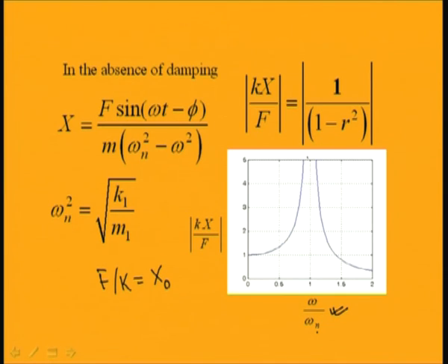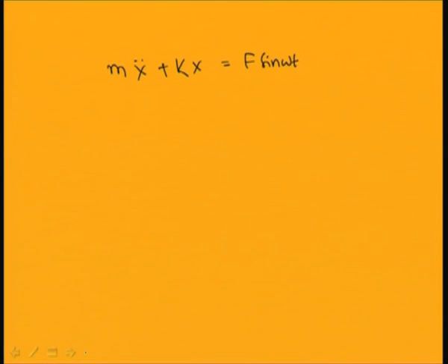So, to observe this vibration, we should add this observer, and when we are adding that observer, we can write the equation of motion. To find that equation of motion, we can use different methods. So, let us use the Lagrange method to find the equation of motion. In this case, the kinetic energy of the system can be written as half m1 x1 dot square plus half m2 x2 dot square, and the potential energy I can write as U equal to half k, so I will write k1.